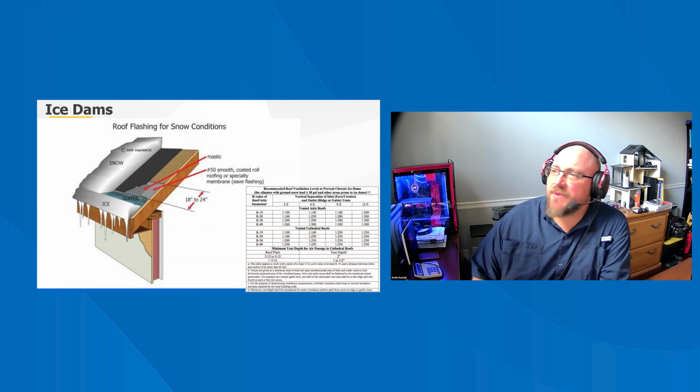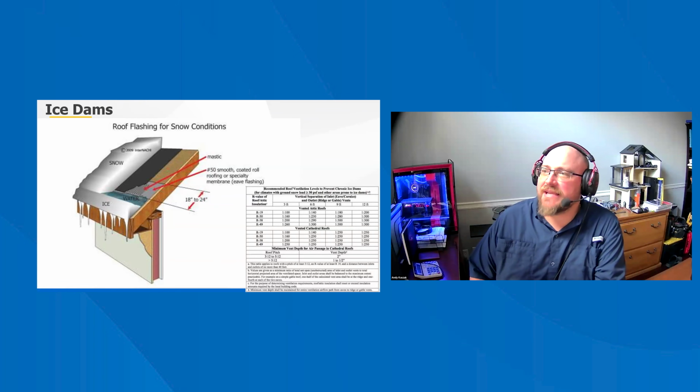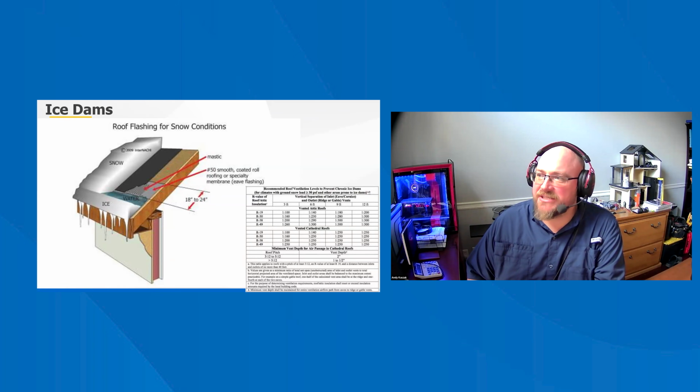So, an ice dam is caused by the warming of attic space, and while attic ventilation and insulation contribute to the prevention of ice dams by keeping attics cold, they can be overpowered by other attic warming effects, such as air leakage from the house into the attic through ceiling bypasses, chases, open gaps, and uninsulated ducts installed in the attic. If significant conditioned air escapes into the attic, ventilation may not be capable of preventing the warming of the roof decking and the subsequent formation of ice dams. Therefore, sealing air leaks between the house and the vented attic is essential for making attic ventilation work.